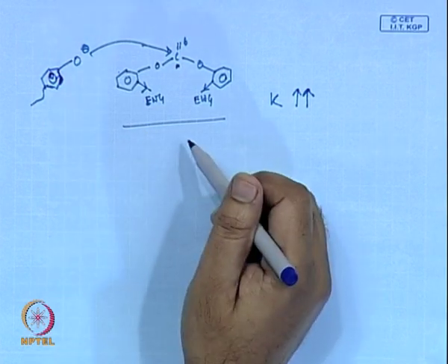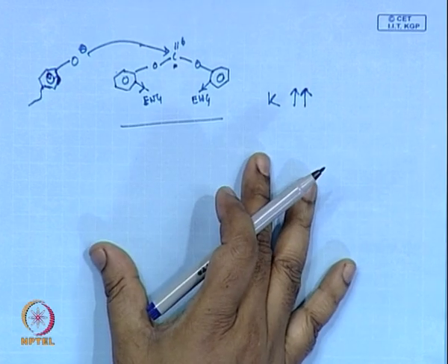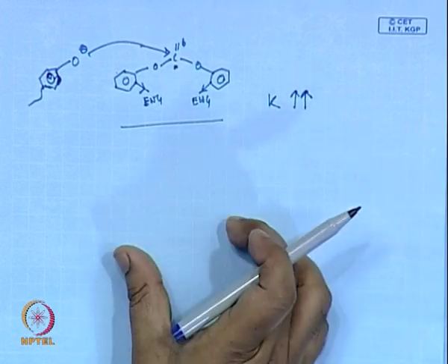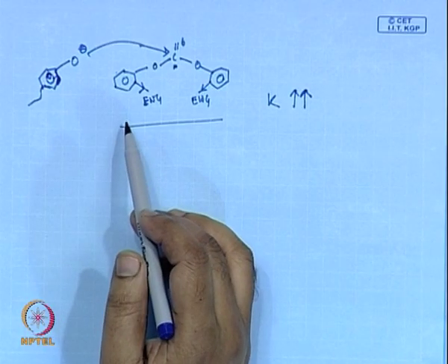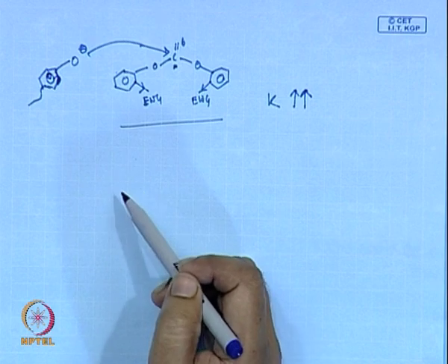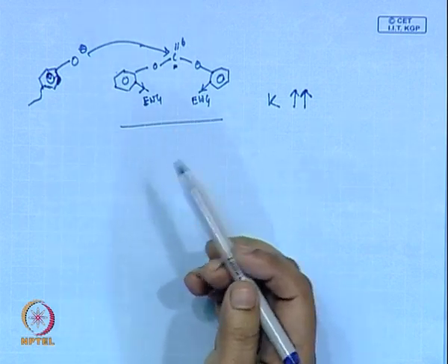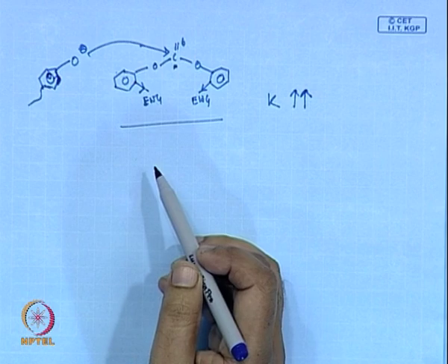So, this is one example where the chemical engineer is restricted by the limitation of the reactor design, where the condensate can be taken out only to a limited level, but still that will not be sufficient to build up enough molecular weight. So, in that case the chemist has to design the monomer in such a way that the equilibrium constant is higher. I just showed one example on this page.